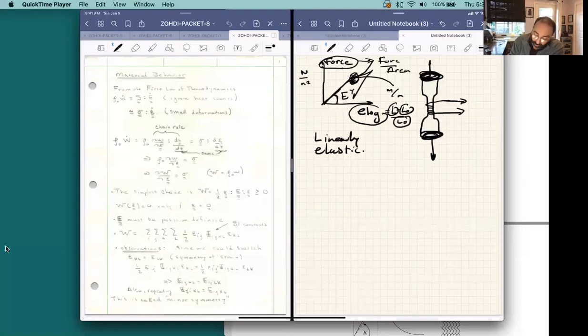Now, let's review how we could get to these linear elastic material laws. If you look at the panel on the left-hand side, what we want to do is first start with the first law of thermodynamics. Let's write out that we have rho zero times W dot. We know that from the first law of thermodynamics, that's the stored amount of energy. And that's equal to, in this case, the second Piola-Kirchhoff stress multiplied by the Green-Lagrange strain's time derivative. And then we have all this other stuff.